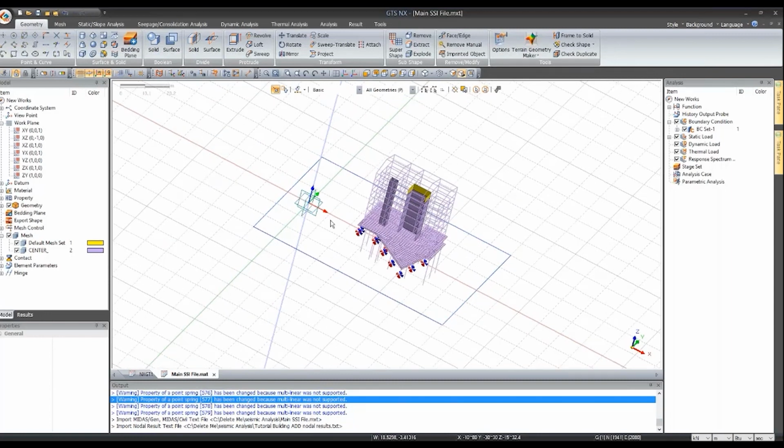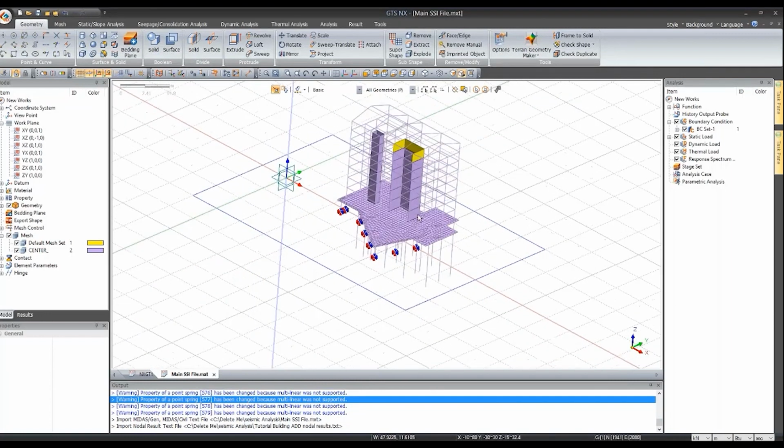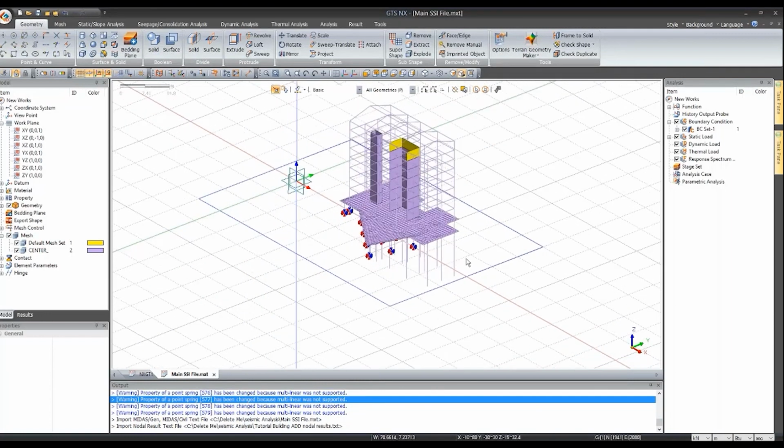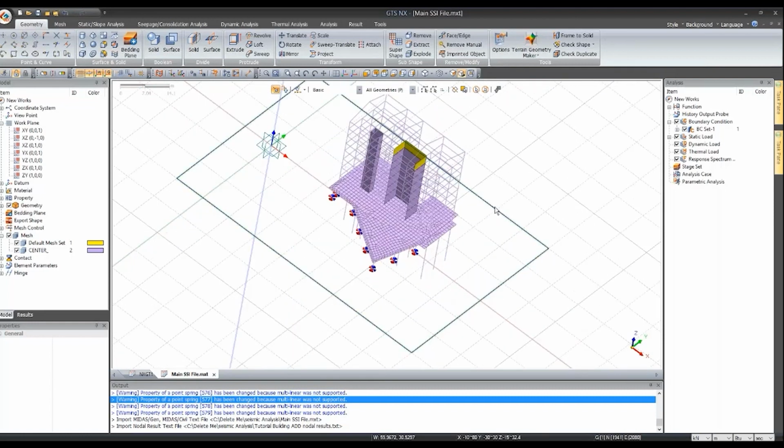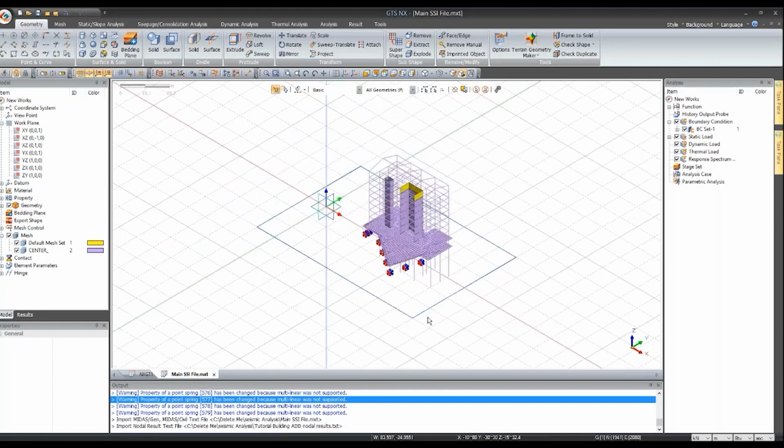What we need to do is we need to run a simple nonlinear static analysis, and we need to see that the boundaries of your model have no impact on the structural results. So till then we need to increase the boundary. So right now this is just a webinar where I'm showing you the procedure. So hence this is okay.